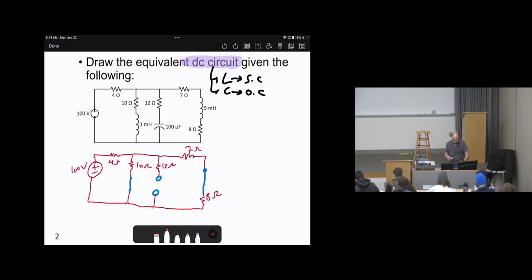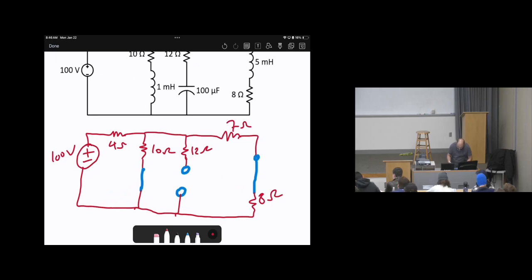How? Look at the 12 ohms resistor. Now, is there any current flowing through it? Recall, the current needs a voltage difference and a closed path. Voltage difference can be found from the source. Is there any closed path for the 12 ohms resistor?